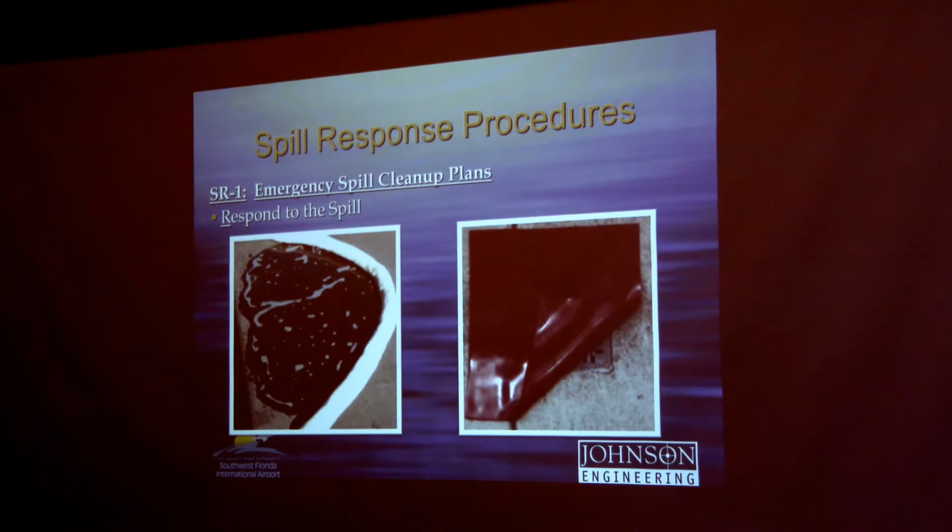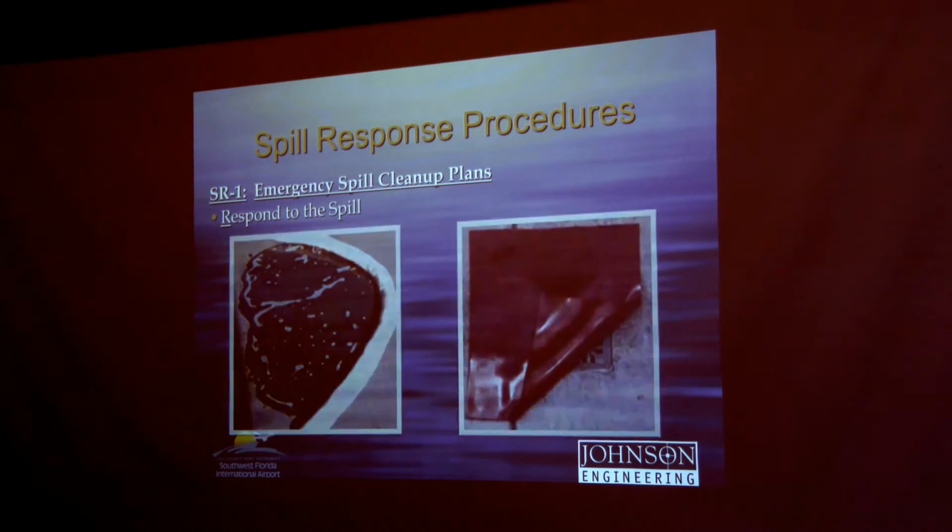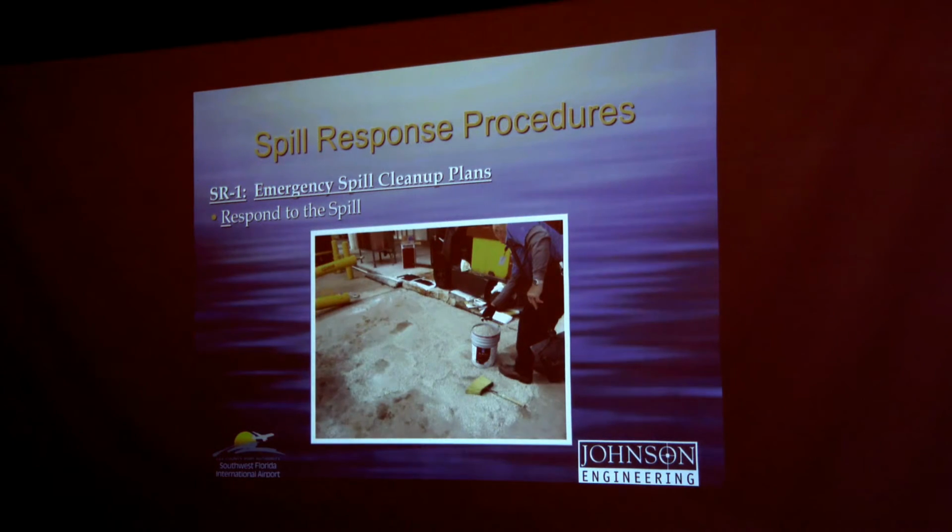When you're sure the leak is stopped and it cannot reach an environmentally sensitive area, use your spill response materials to absorb the spill and clean up the spill. Dispose of all used spill materials appropriately. And remember that the sooner you stop the spill and clean it up, the easier and cheaper the cleanup activities will be.